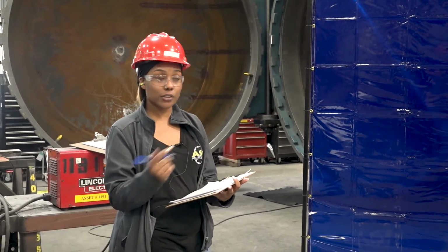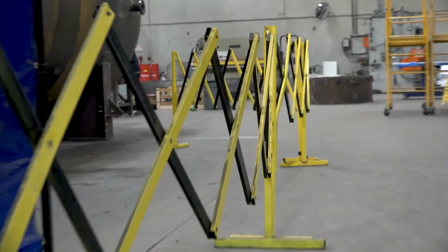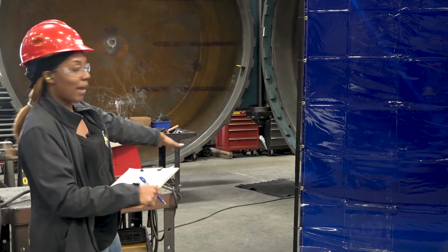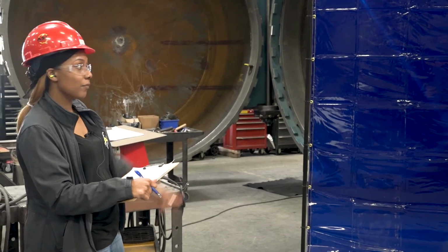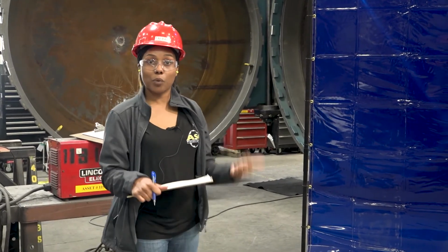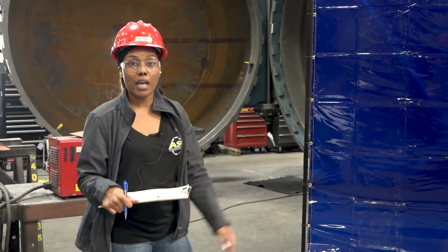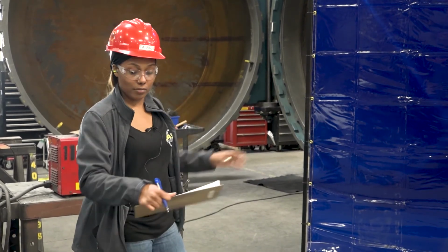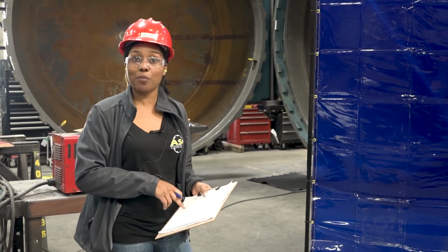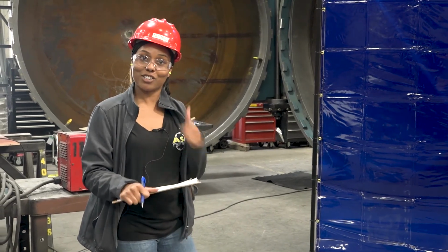So to control these hazards, what he has is he set up barricades alongside of the boom lift to direct traffic. He has also set up his welding curtains for arc flash. He also has padding down here for his overhead work for ergonomic efficiency, and he's got all of his PPE ready. He has his welding helmet, he has his welding gloves, he's got his shop PPE, and he has his FOD bucket. He's indicated here that he'll be cleaning up every 30 minutes, and being that he's working by himself, he has approved the task and signed it off, and he's good to go.